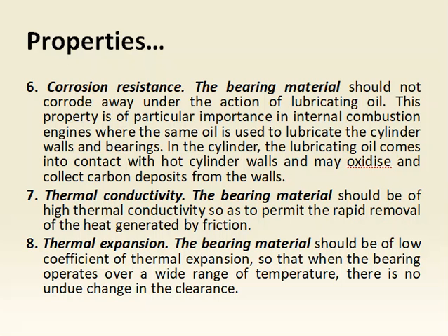Then thermal expansion. The bearing material should have a low coefficient of thermal expansion. That means the dimensions should not change due to temperature change. It should not expand. The proper clearance must be provided. If the material reacts to temperature and expands, what will happen? The clearance might be reduced.